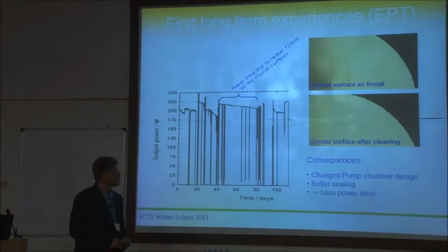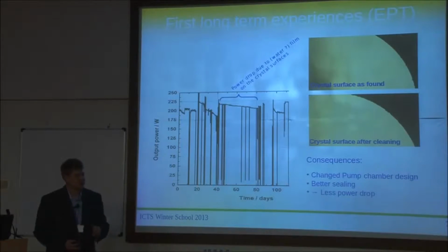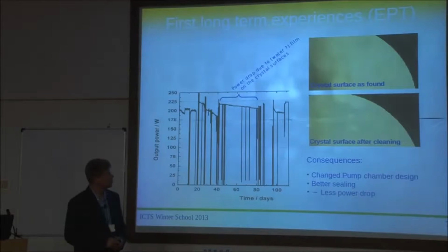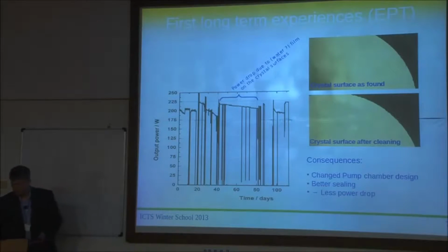But the consequence is that we changed the pump chamber design a bit, and also changed the size of the O-ring a bit to have a better sealing against this water, so that the O-rings really squeeze into a little groove, and that then holds the crystal. So that was one lesson we learned, that we had to slightly modify this pump chamber design.